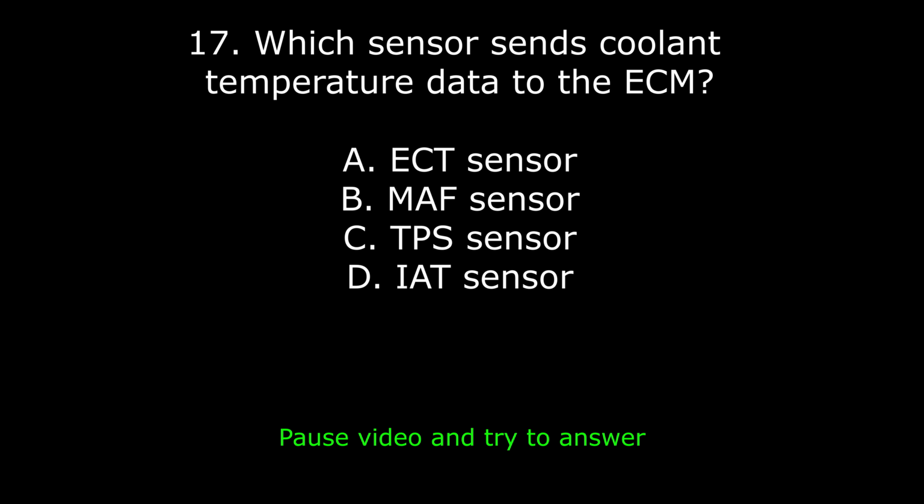38. A door lock works with the switch but not the remote key fob. What's most likely? A. Blown fuse. B. Key fob battery dead or requires reprogramming. C. Shorted actuator. D. Corroded ground. Answer: B. Key fob battery dead or requires reprogramming. If the manual switch works, the problem is with the remote signal or programming.